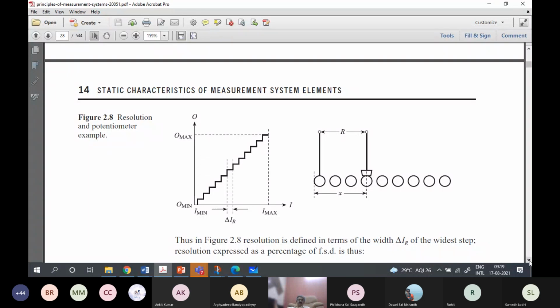That may be too expensive to do. So if your noise is limited to, let us say 100 millivolts, then there's no point having an 18-bit AD converter, because the last 3 or 4 bits will be simply dancing because of noise. So you don't have a resolution. So an input change of 50 microvolts cannot be reliably sensed, because the bit pattern, which is the output of the AD converter, will be simply random.